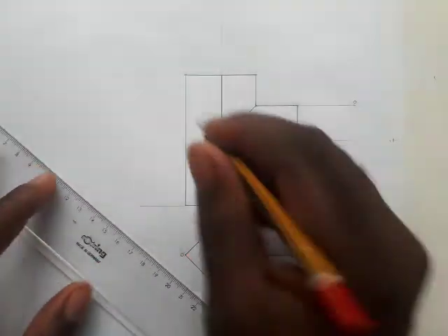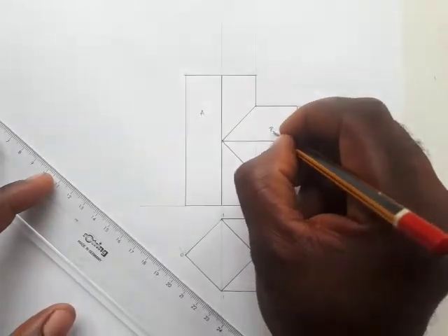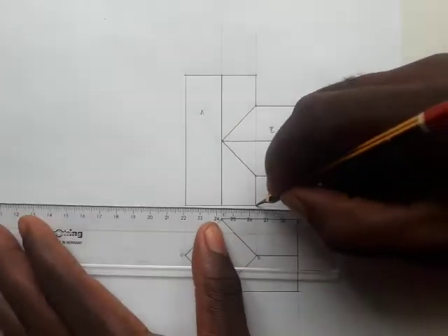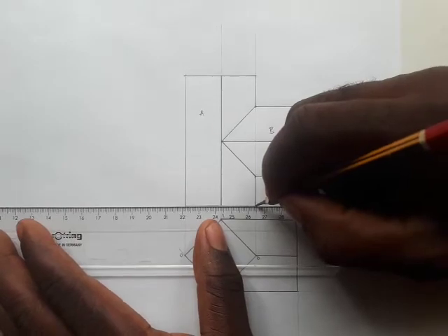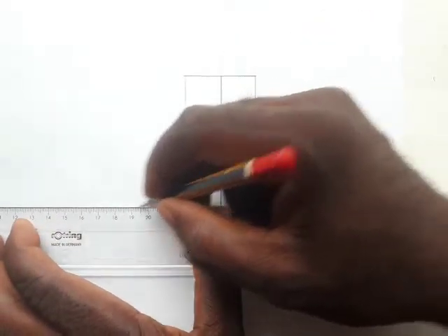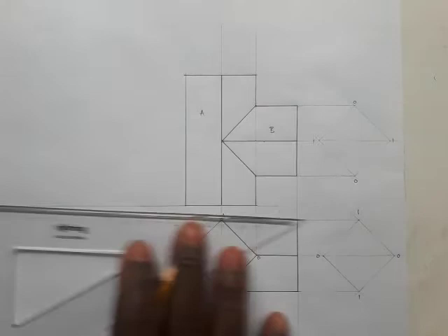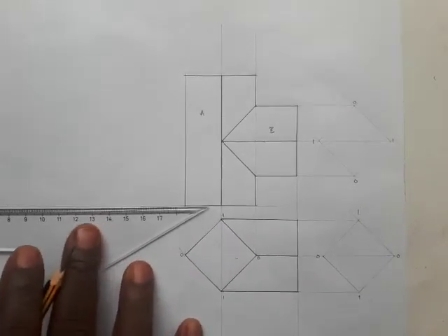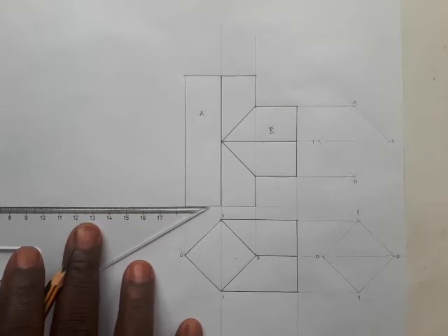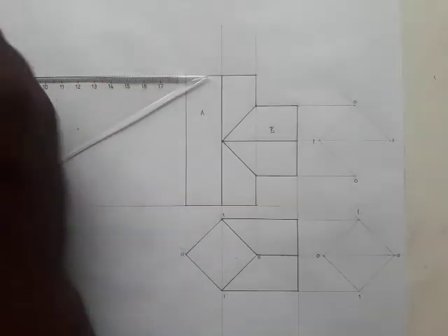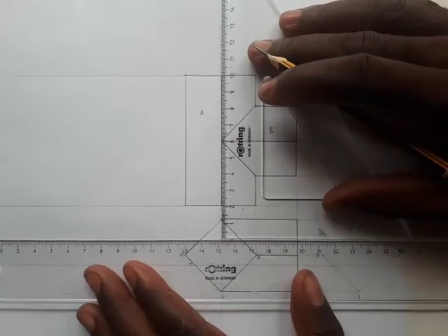So let us develop pipe A. This is pipe A and this is pipe B. So to develop it, you align your set square, your ruler, and extend this line with thin lines. So also do the same for the top, but I like to transfer just to be sure that the lines are parallel. Okay, so align and move to the top as well. Thin line. Okay, good. Now align your set square and choose where you want to start your development.